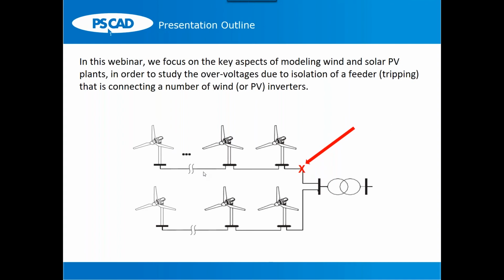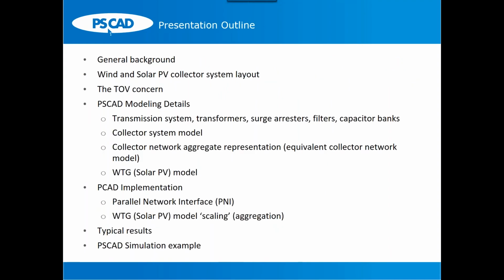There are very specific details that you have to keep in mind when you perform these studies and develop models in an EMT type program like PSCAD. So today we will have a general background discussion, which I think we already did. We also discussed what this TOV or temporary overvoltage concern is about. So today we will then discuss the modeling aspects.